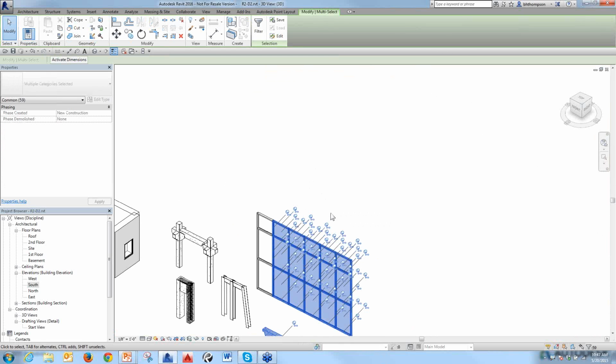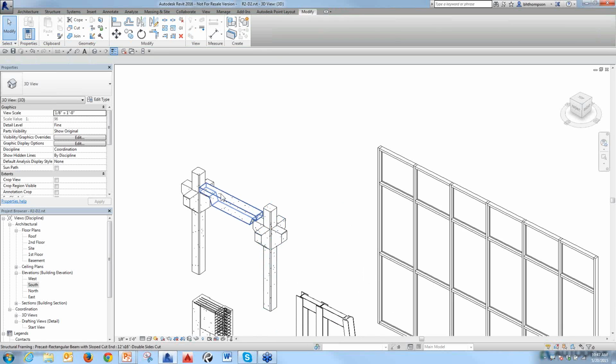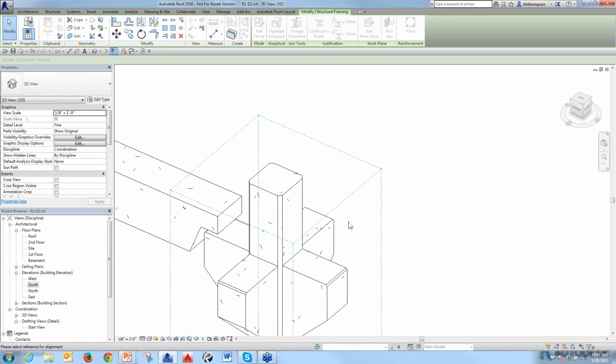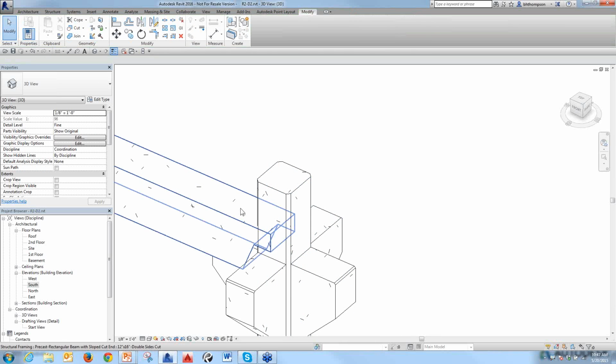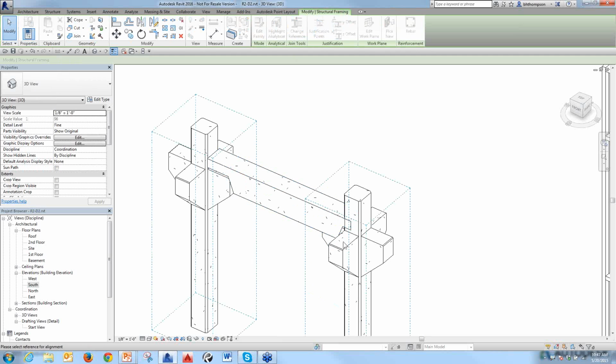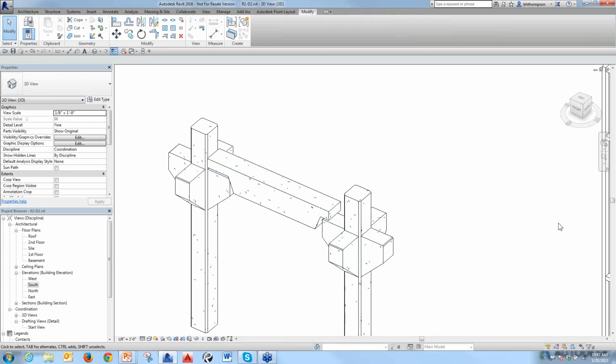They've made some improvements for pinning. Now it only displays so many pins, up to 250. So you can't get any more than 250 pins on the screen, I believe is the limit. We can now go in and change the reference for beams. This will work a lot for structural and architectural uses. You can see I'm changing the end of the beam and stretching it from one point to the other. We can do this again, and I can say change position and select that plane, and it'll move that back and forth. So those are just some things from R2 that weren't in the slide deck.